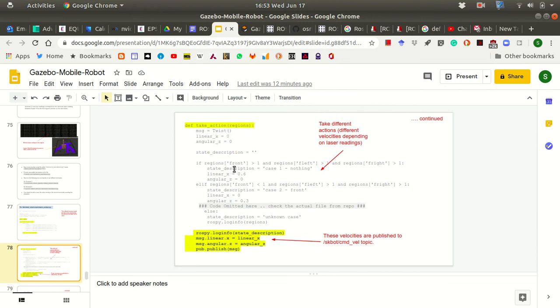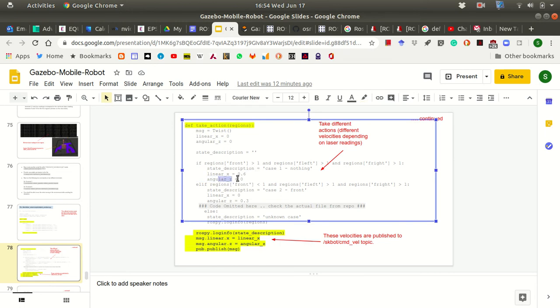So what it does is that it checks all the 5 regions, whether the obstacle is there or not, and accordingly it decides the motion of the robot in linear X. Basically we need two kinds of motion. One is whether we should go forward, that is called linear velocity X, or we should rotate, that means we give an angular motion around the Z axis. So if the obstacle is there, we give a motion around the Z axis and the forward motion is stopped. There are several cases, 8 to 9 cases, and all these cases we mention using if and else if statements, and ultimately the states and the messages are recorded somewhere.